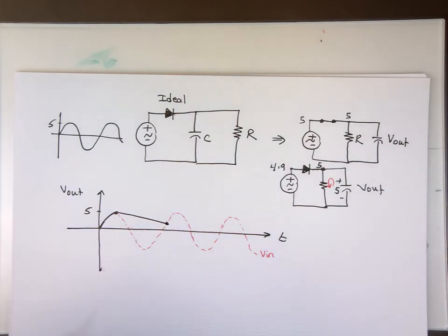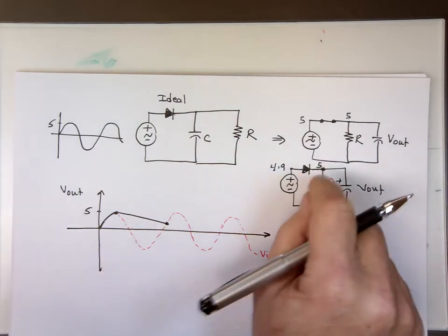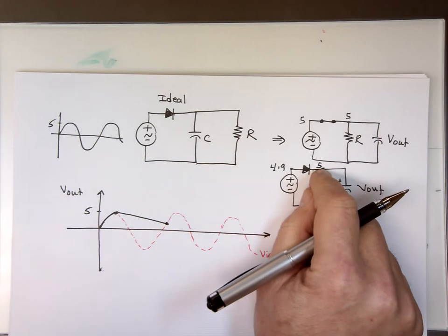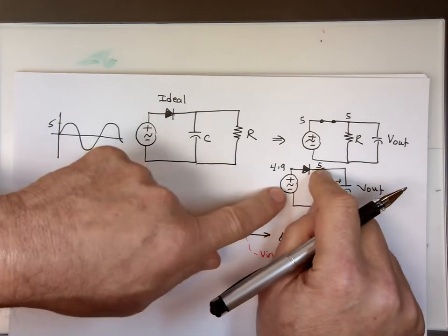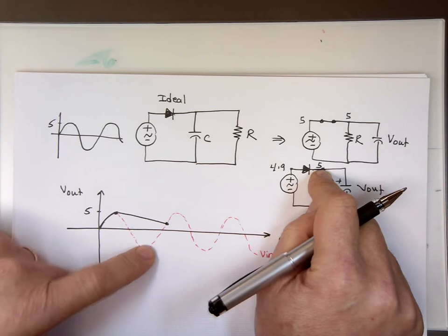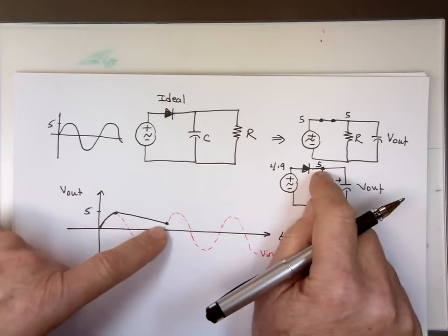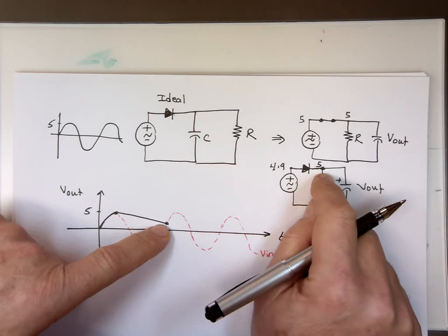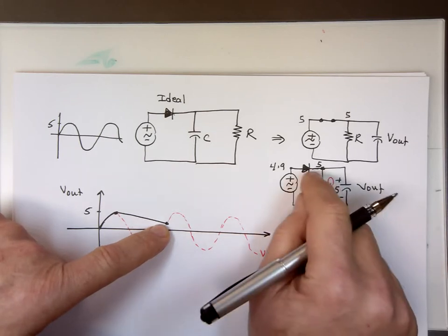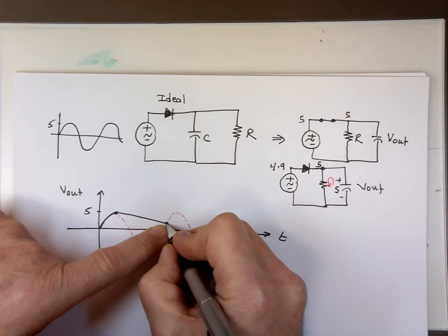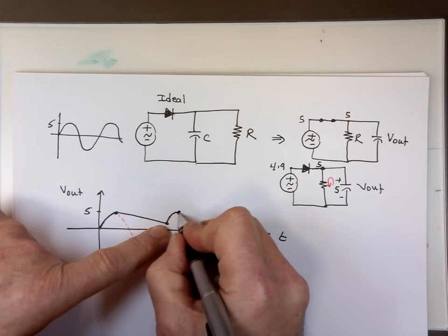till it hits that value. So we'll start to decrease, for example, let's say to 2 volts. As long as the value of this source is below 2 volts, nothing is going to happen. This is going to be your circuit. Once the value, actually this one exceeds that 2 volts, I'm just using as an example 2 volts here, this one now will come in and start to charge again.